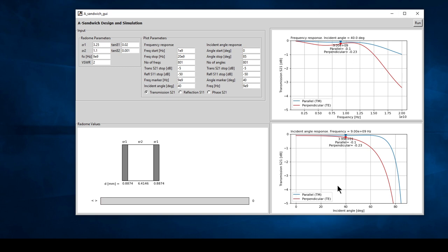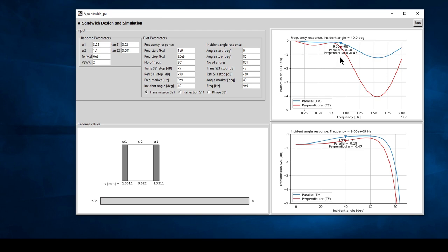And we can also look at the influence on the response. Usually, as we make the VSWR higher and higher, your insertion loss here is going to get more and more. So that is a trade-off you have to have. Obviously, we can make also the frequency lower. We can make this, for example, 6. And then we should see then also, obviously our response now is going to get worse at the higher frequencies.